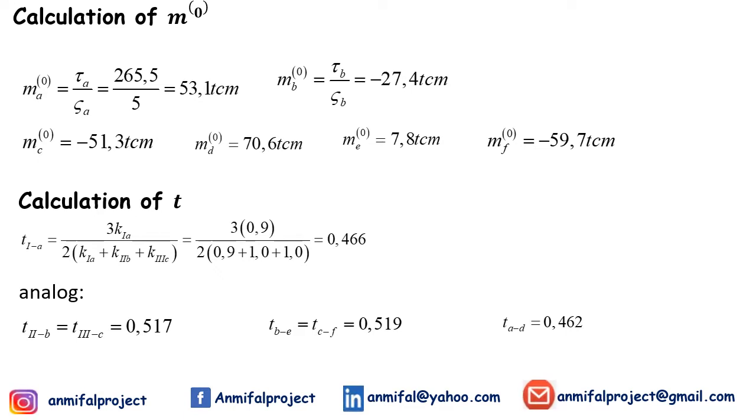The effect of the story height should be considered as the T parameter, which involves the column stiffness divided by the total column stiffness. Okay, so we get T at columns 2B, 2-1E, and 2-3C for the first floor and the second floor.